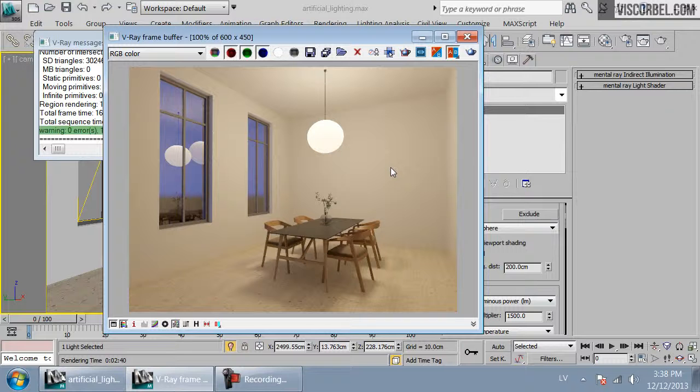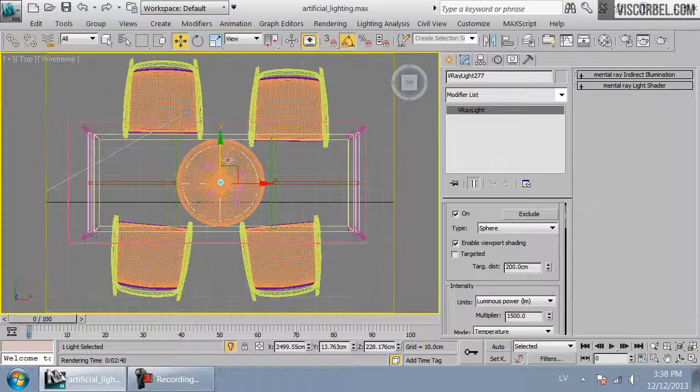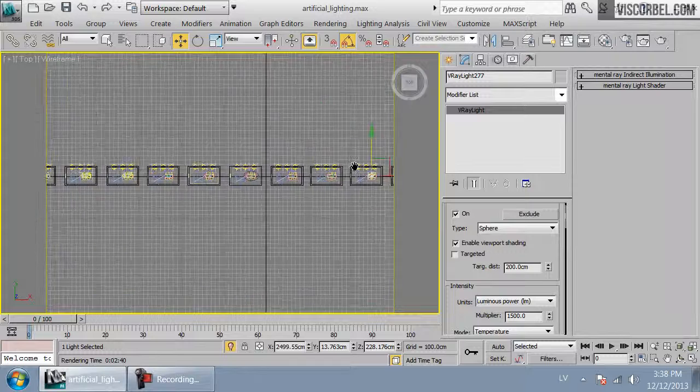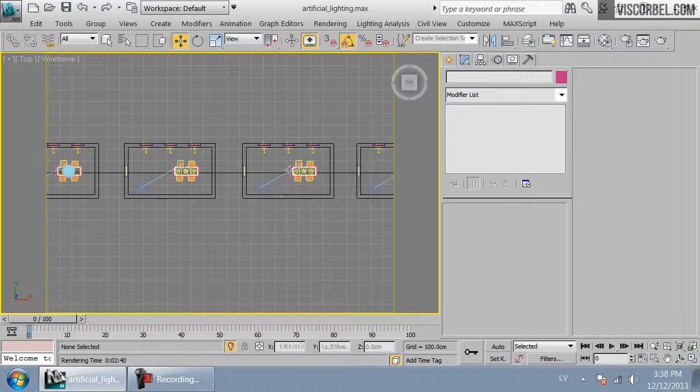So this works the best if you have a completely enclosed bulb. So there are no spots that should be brighter and no spots where you have this direct light. Everything is illuminated by this diffuse large enclosure. Okay, so the vray two-sided material can be used in some other scenarios as well to quickly render the lampshades, especially if the lampshade is made from cloth or paper.